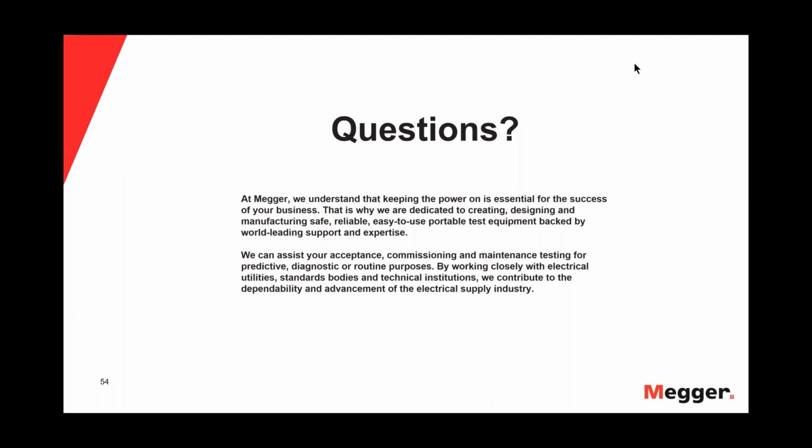On that particular circuit, I hooked the phase comparison method up, and I was able to see a slight impedance change between the good pairs and the bad pair. And I said, well, that is where that problem is in the cable. It was right in the middle between the two light posts. And next time it happened, it rained, the light went out, and it blew up, and they knew exactly where the fault was.